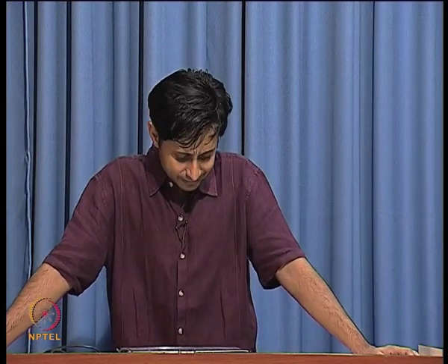So, typically a good number for rejection for a duplexer is about 60 dB. When you buy a duplexer, this is as much as the mechanical switch can give you. Electronic switches give you even less. So, forget electronic switches. The mechanical surface acoustic wave duplexer or whatever it is can give you, let us say, 60 dB of isolation from the transmit to the receive.